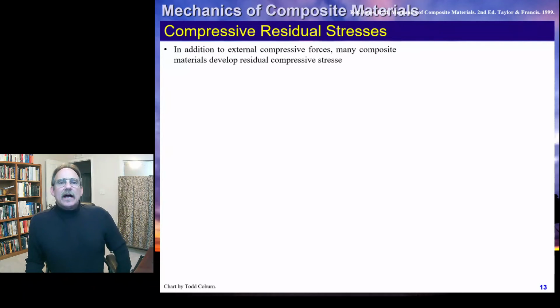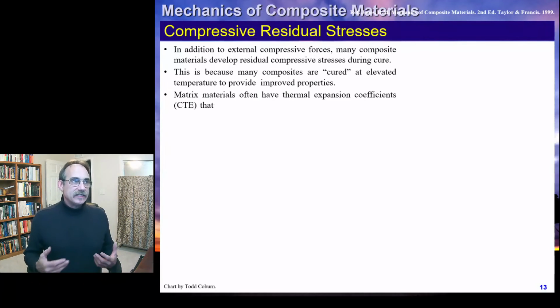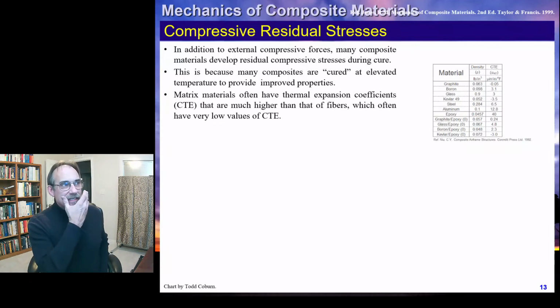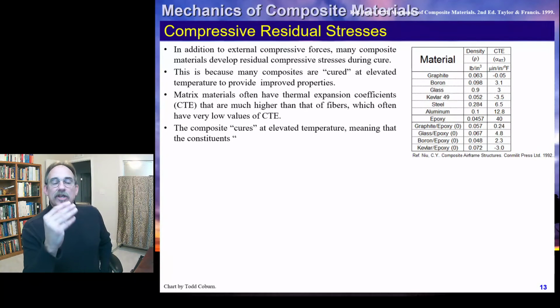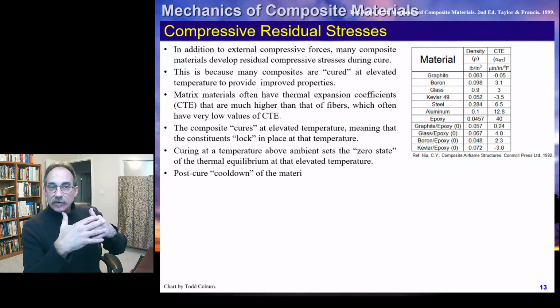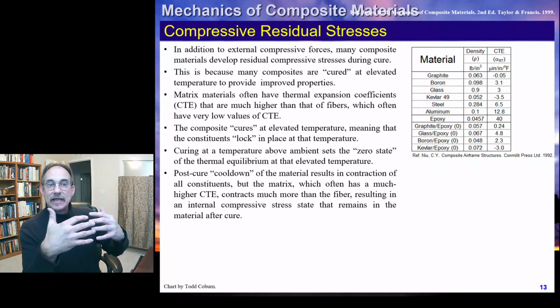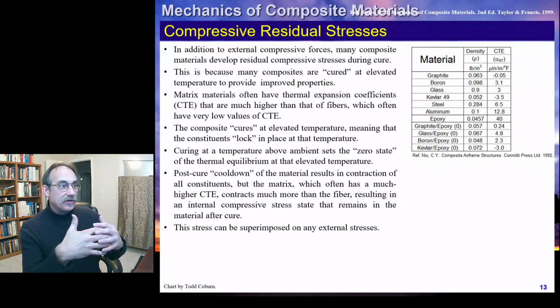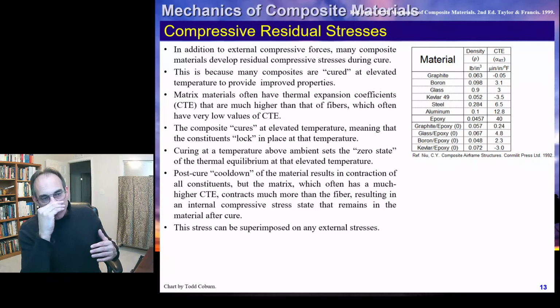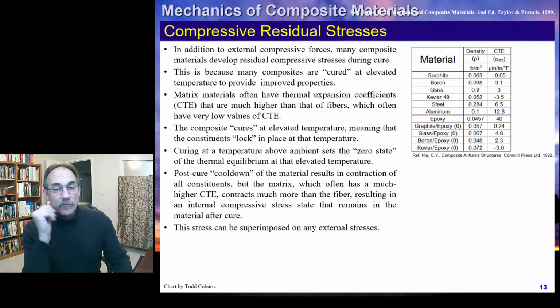A quick word on a couple other topics. The first one we might want to talk about a little bit is the residual stresses. Okay, when we're curing, we're going to tend to develop residual stresses. Remember, we've got all these materials and they're different, and they have different coefficients of thermal expansion. That means they expand and contract differently under temperature. And because curing is done at an elevated temperature, you can actually end up locking in stresses, residual stresses, due to the mismatch of the coefficient of thermal expansion.